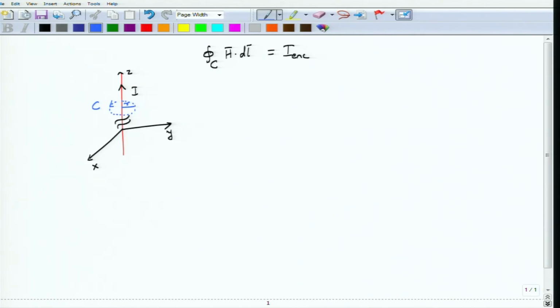If you cut this z plane and look at the top view, this is what you would find. The top view would show you the contour, and then there is a central piece of conductor or the wire which is carrying a uniform current of I. Now for this contour, we know that in the cylindrical coordinate system, for constant z and constant r, the line element dl will be equal to r d phi phi hat. Of course, it's the angle phi which is changing, and your dl line segment will be directed along phi hat.